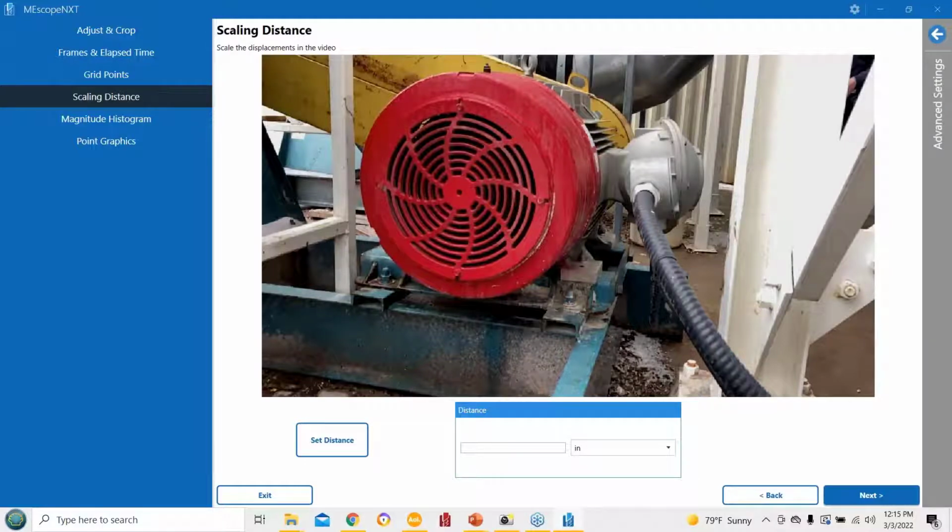And in fact, Mark Richardson just told me about this. There's an Fmax at 240 with your cell phone. A usable Fmax range in the frequency spectrum is half of that, or the Nyquist frequency, which would be 120 hertz. This unfolds all that, so we get actual data up to 240. So it's really nice, and we're going to play with that a little bit next week.